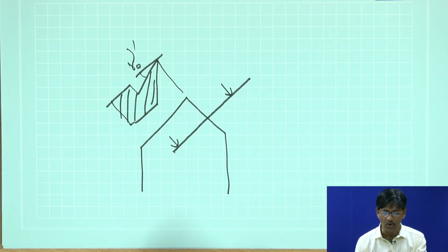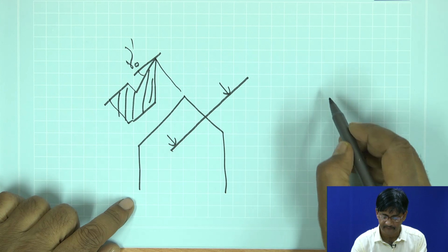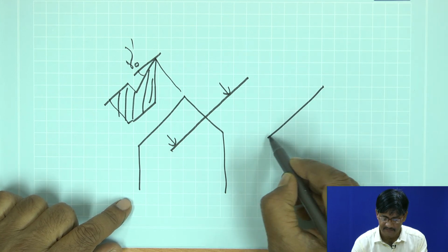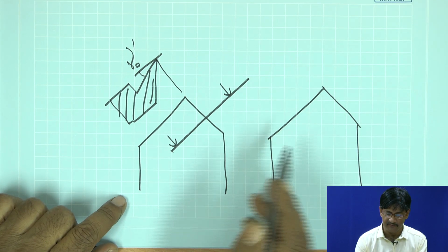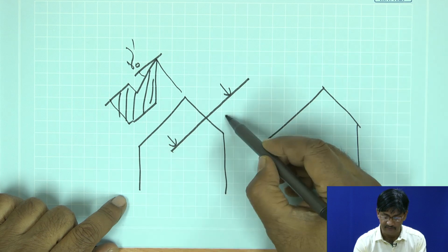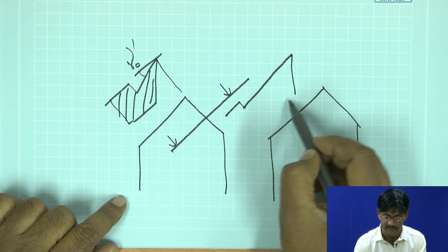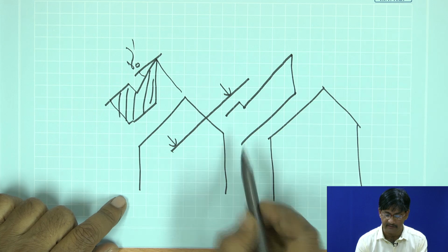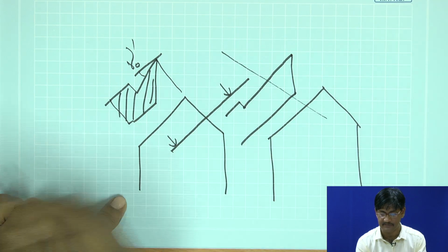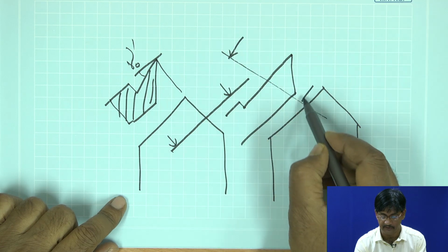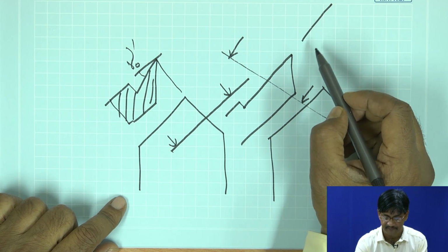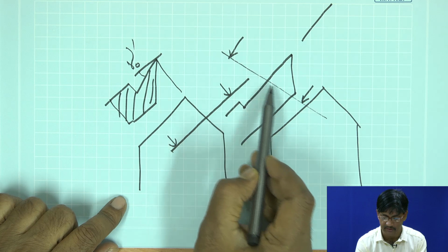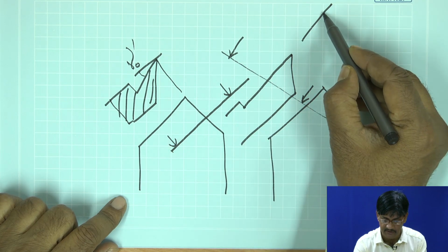Now, for the normal rake. This is the cutting tool once again. If you have the tool this way and look at it from this side, we will see the inclination angle appear this way. On the inclination angle, if we cut along this particular surface perpendicular to it, this is the normal plane, and the section will look somewhat like this.